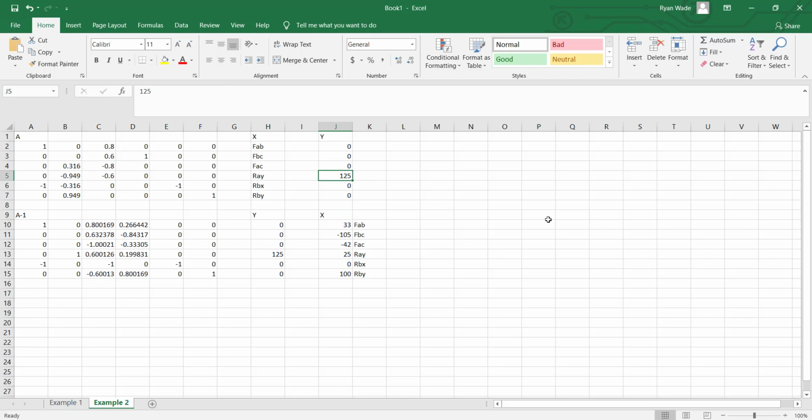I could also change it to a horizontal force, right? Well, that would have to be changing my matrix. So if I wanted this to be a horizontal force, I would have to go back. Right now it's in equation 5 as my answer. If I want it to be a horizontal force going to the right, I can say there's a 250 kilonewton force to the right by putting it into my sum of the forces in the x for that joint.